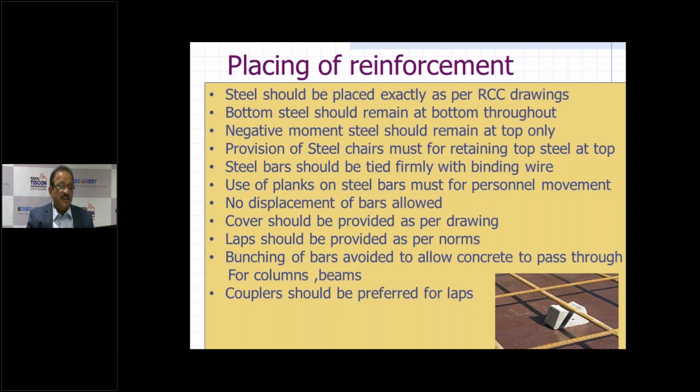Then provision of steel chairs is a must for retaining top steel in the top position. If we don't provide chairs, typically of this shape with two small legs, the top steel would touch the bottom steel, the negative moment area would be exposed, and you will get a lot of cracks there.